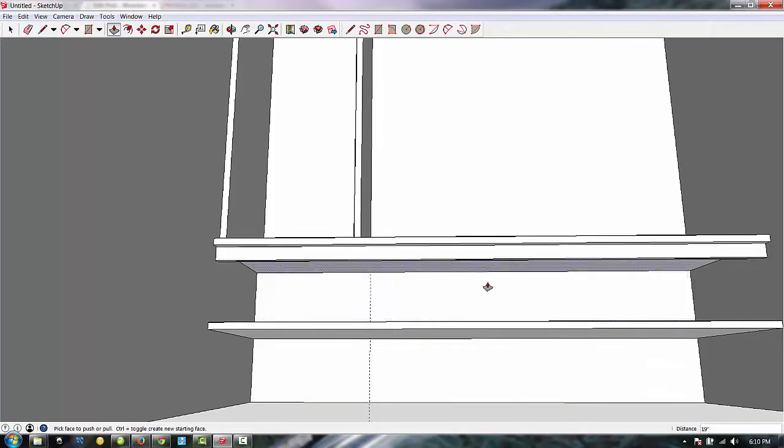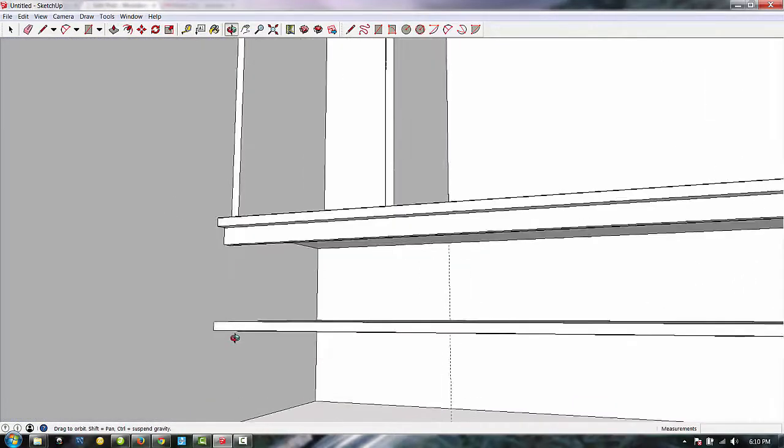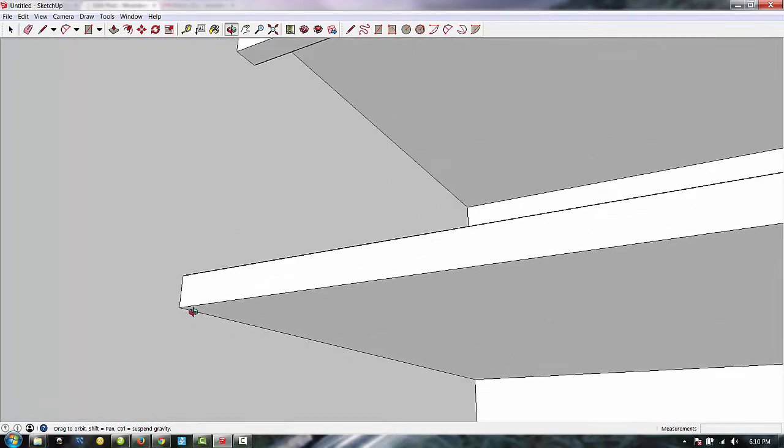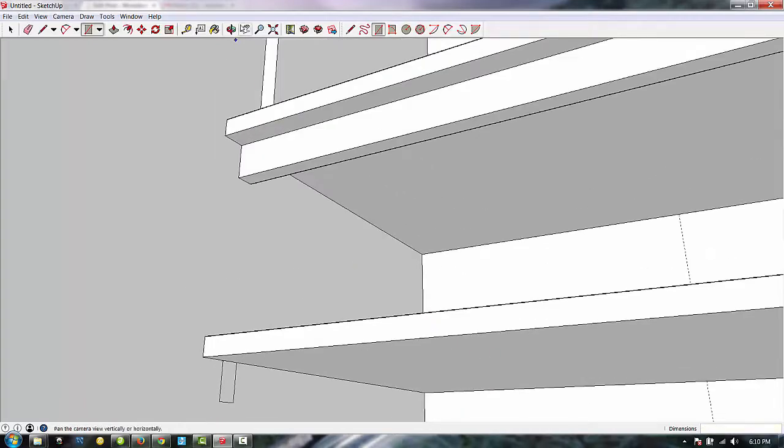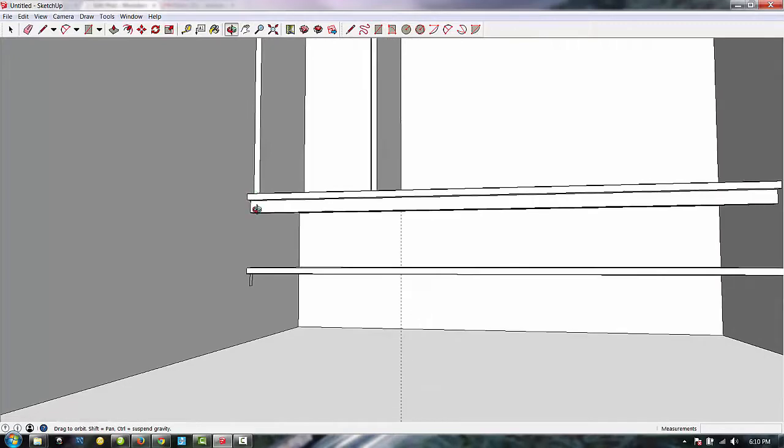I'm not going to get into details with the middle supports. This is just a demonstration of how to do a layout, a wood plan layout in SketchUp. So again, we'll quickly do the 1 inch guideline, and then we'll drop a 1x2. Once again, 3/4, comma 1.5, hit enter, and then we will push pull.